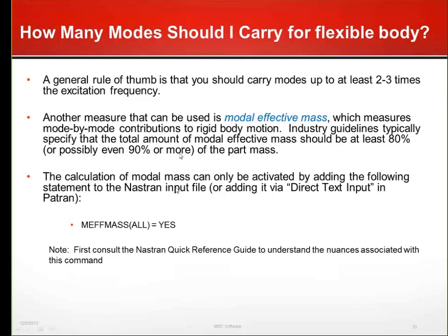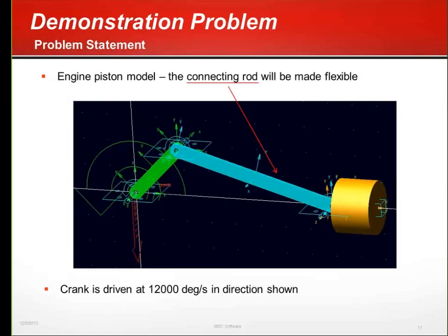You can do that by using this modal effective mass command inside of the Nastran input file. If you do that, I'd first encourage you to take a look at the Nastran Quick Reference Guide to really understand what this does and some of the nuances of this command. But it is useful.